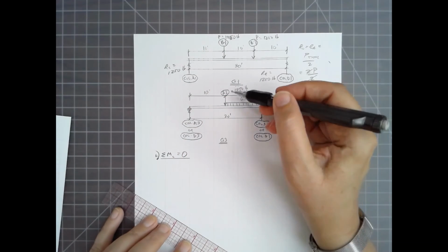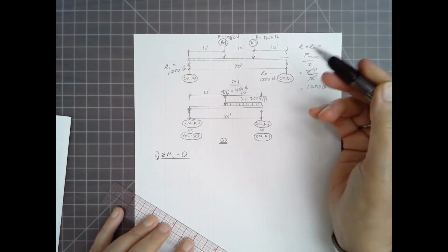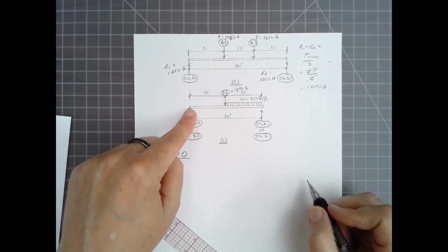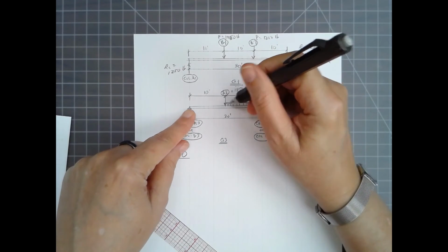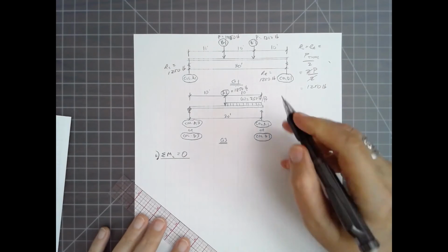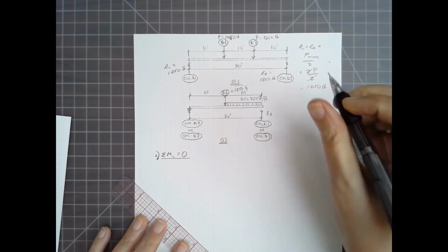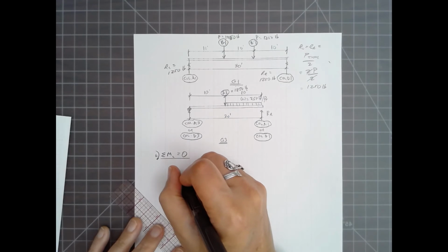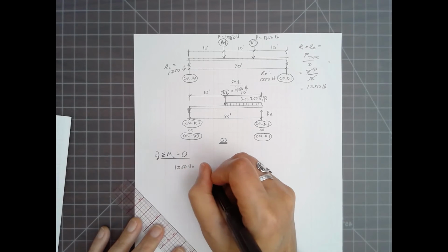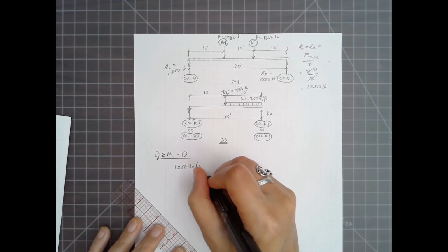I have 2 elements here that are rotating around, with the potential, if this is the fixed point, load here, a load here, and then the balancing force is the right-hand reaction. So that says that I have 1,250 pounds with a moment arm of 10 feet.